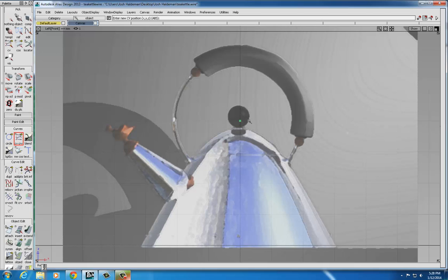Now it's important, anytime you're planning on revolving a shape around the center of an object, that the second CV point be placed either horizontally or vertically aligned with the first one, depending on what axis you're rotating about, so that when you revolve the shape, you don't have either a peak or a valley in the center. So the second point has to be right here because that's directly horizontally aligned with the first one. And when we revolve our shape, it will revolve around the middle and not have a peak or a valley. We'll just have a dome there.